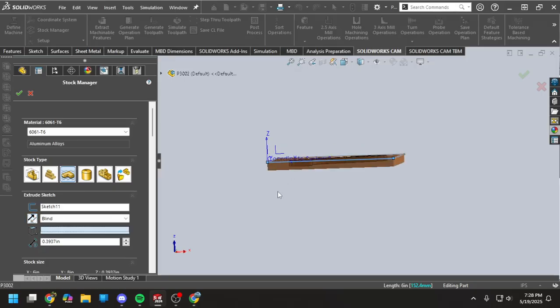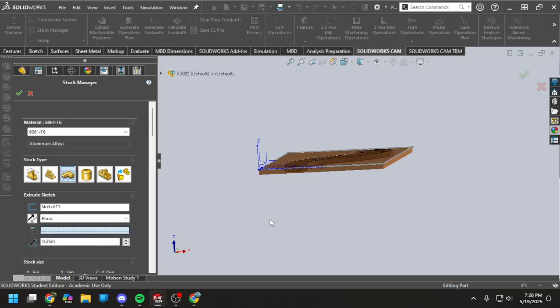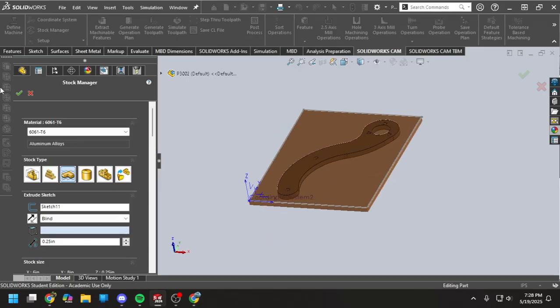You can see how it encapsulates the part here, and that our Z is touching off the top just as it will on the CNC machine. Material here at this point does not matter. We will be overriding feeds and speeds manually for every operation here. And then the thickness of your stock can be specified down here. So 1/4 inch polycarb is what we're running with.